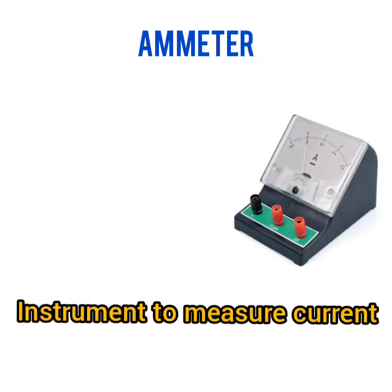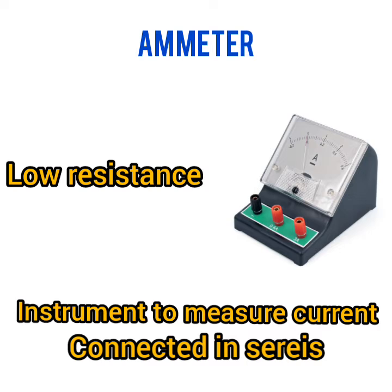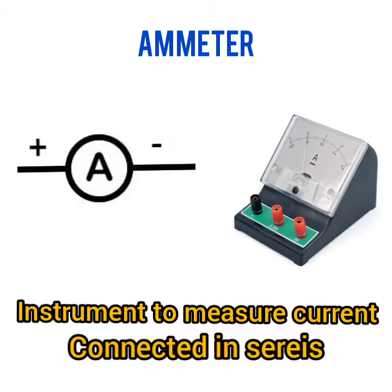Current is measured by an instrument called an ammeter. The ammeter is always connected in series with the circuit in which the current is to be measured. This is because an ammeter has a very low resistance so that it may not change the value of the current flowing in the circuit. We represent an ammeter in a circuit by drawing a circle and writing the letter A inside it.